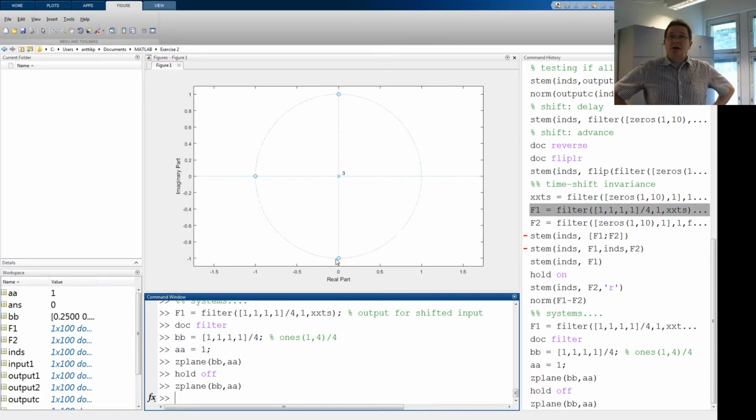Okay, so zeros on the unit circle. There's also a unit circle, real axis on the horizontal and imaginary axis on the vertical. Then we have triple pole at the origin. So that's how you mark zeros and poles. Okay, one warning: if I get any of those zeros and poles mixed, it means that you have messed up or mixed the a and b,